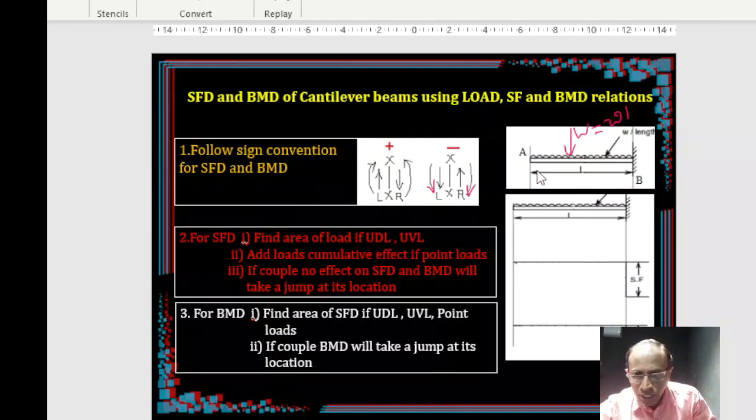difficulty. So at this location, the load has not yet started. By the definition of the shear force itself, because there are no forces acting here, I am starting from the free end. What is the value of the shear force here? 0. Okay, now at this location,